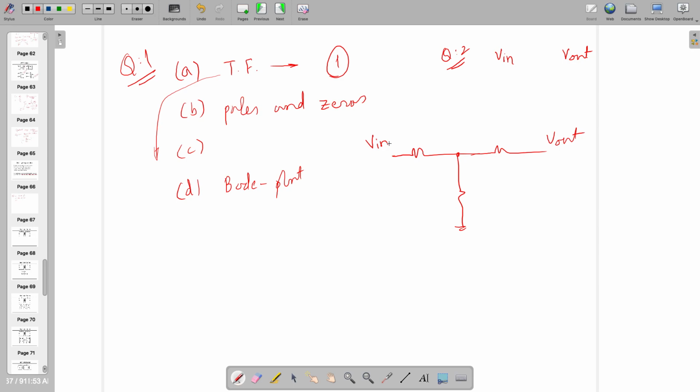You take nodes which are known, like 20 volt, 30 volt. If it is mentioned, then we don't include them in the matrix. You should make the optimized version. There are some places where it was 0 volt. In the book it was given that except ground we consider all nodes. But afterwards we need to have the optimized version of that matrix. How to solve that 9 by 9 matrix? We take the nodes which are not known to us, like Vin, Vout.